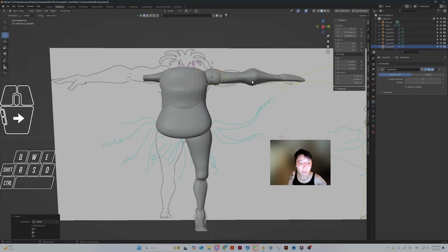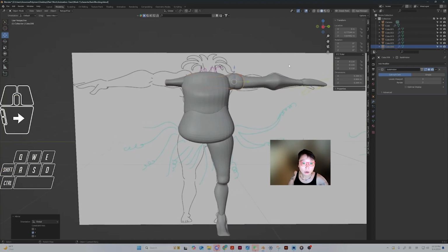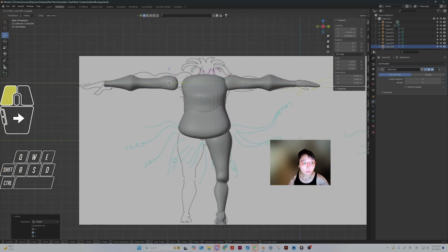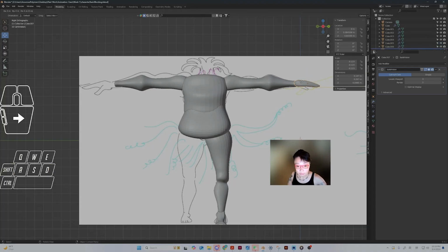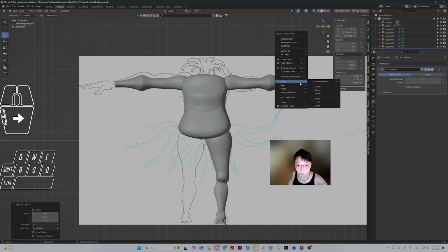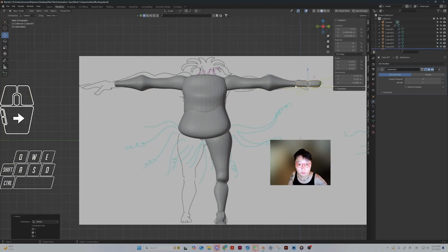Let's try Y global. Okay, it doesn't matter. So now we're in the frontal view. We're just going to move it over to here. See, my drawing isn't exactly symmetrical, that's why. But it's okay, we can fix all of that later. So again, Shift D, hit Escape, go into mirror, we'll do Y global. Now we're just going to move this over here.